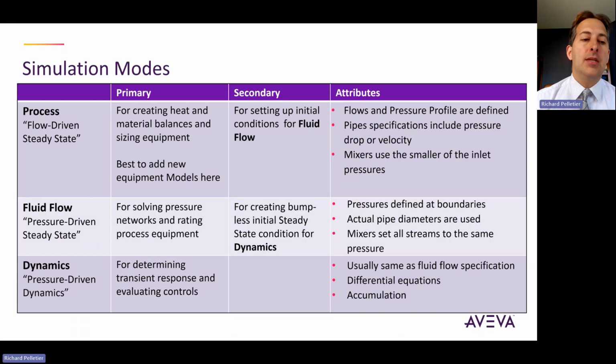and that's what changes the behavior from mode to mode. The last mode is dynamics, and this is a time-dependent way of operating. When you go to dynamics, you typically make some kind of change, and then you run the simulation over time to see how that change impacted the behavior of the simulation. Now, normally you're going to start from a steady state solution. And given that this is pressure driven, just like fluid flow, you typically start from a fluid flow solution.